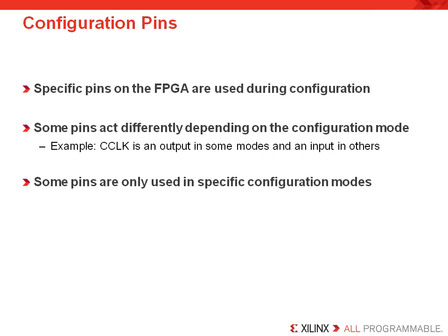Now, this is a little challenging because each configuration scheme can differ so much. That's because each pin may or may not be used in different configuration techniques. This is why the datasheet and the user guide for each FPGA discusses each configuration scheme in detail. In fact, the user guide covers each configuration technique in more detail than we're going to provide here, so remember to review the section on your chosen configuration scheme.